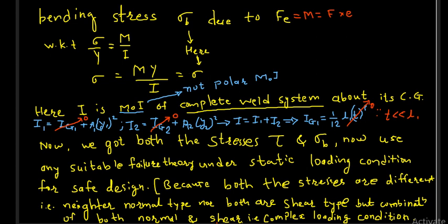Then talking about the bending stress, right? What are the bending stresses induced due to this force F, and what is the bending moment created or induced by it? It will be M equal to force into the eccentricity E. We know the bending equation, that is sigma by y is equal to M by I.